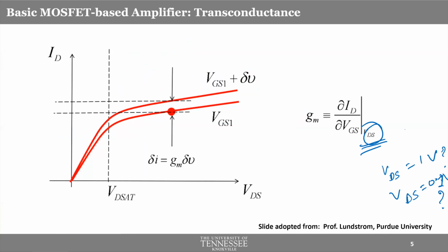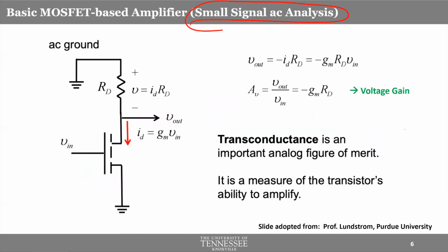Now, moving forward. Now we are ready to look at a small signal circuit for the MOSFET, the same circuit that we have been dealing with. I will not be adding any DC component to it. I will just replace that with only the AC part. Previously we had VDD connected here, but VDD is a DC component, and the DC components are not changing.